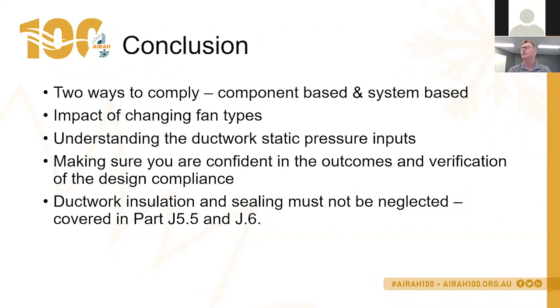Stated ductwork elbows greater than 90 degrees require long radius bends or turning vanes. Any requirements for less than 90 degrees? No. A DX coil for an air handler is not listed when selecting a coil in the calculator. How do we take that into account?